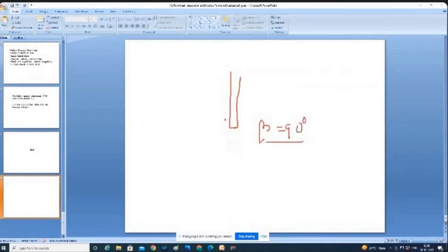If sharp flange is there, then what will happen? This flange thickness will become very less. So whenever a locomotive is moving over points and crossings, with one tongue rail and one stock rail, the sharp flange is likely to enter between them and it may lead to derailment.